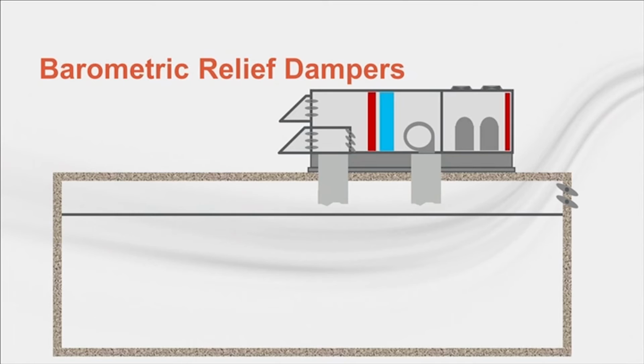In some cases, the dampers can be placed in or near the occupied space, or in the return air plenum, as shown here. In this case, when pressure in the space increases due to economizer operation, the excess air exfiltrates through the envelope and the relief damper. This positive pressure pushes air through the damper and prevents the space from becoming overpressurized.